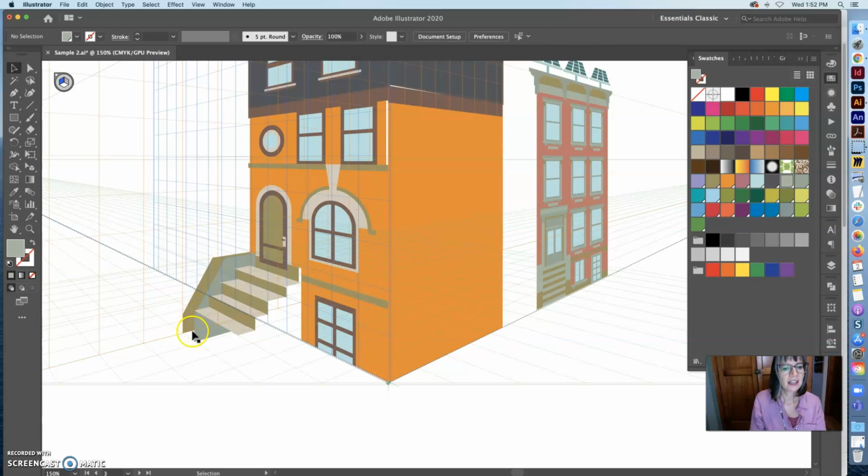So what we're going to do is start by making the riser part. I am going to have that on the blue wall, and I am going to drag from this corner to this corner to build that front part. And you see when I did this drawing here, I didn't get that angle right because it was more of an angle that I was guessing. So I'm going to pull this down. Actually, looking at the way I've got the stairs here, it looks like it needs to be higher, which means this one also needs to be higher. I was just guessing on those before, but this one is actually drawn in with the perspective tool. So that one is correct.